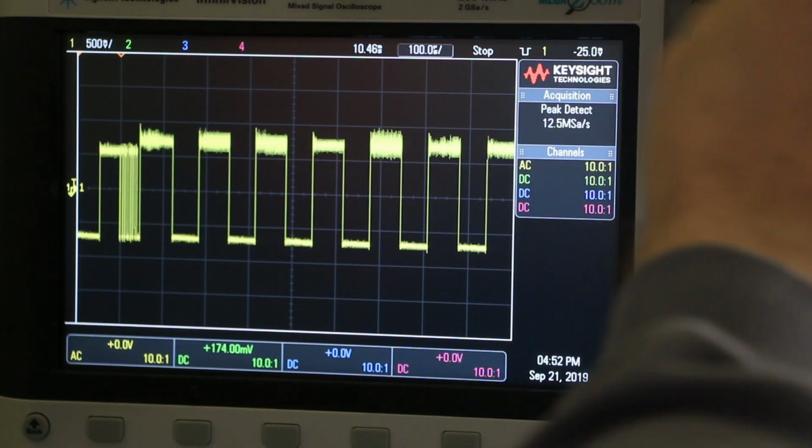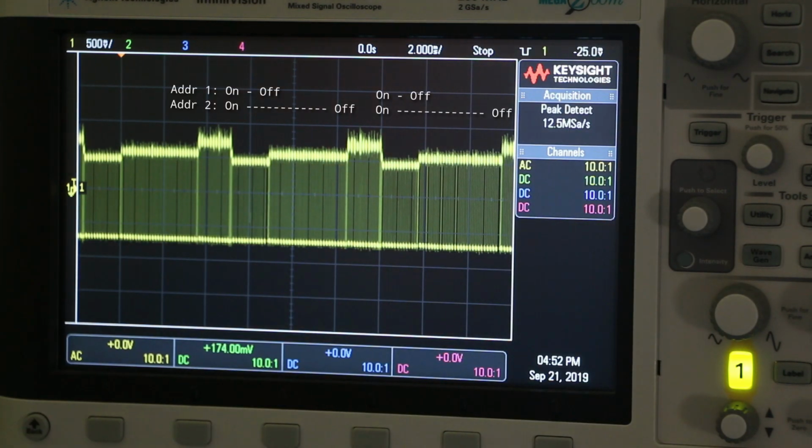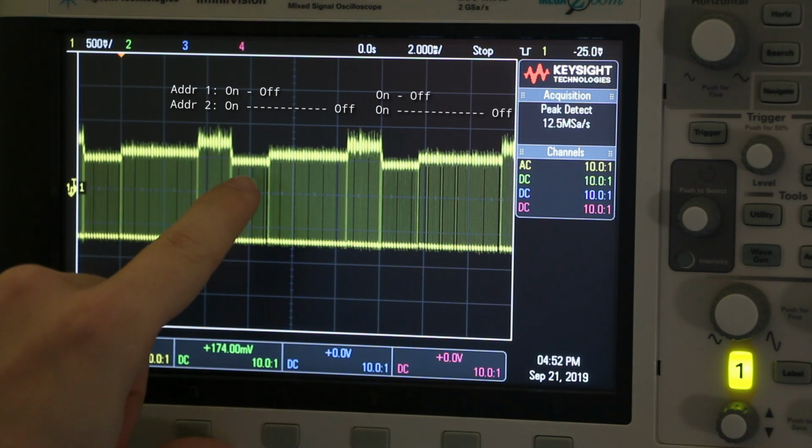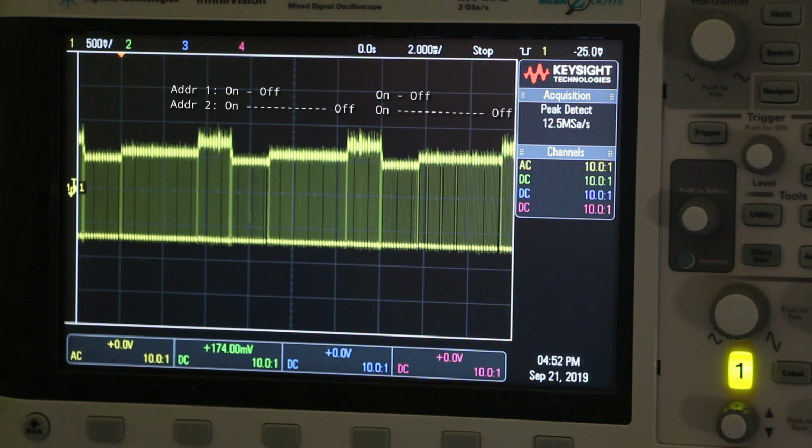So if we put that together, we can start to write onto or assign values onto this waveform here. And we were quite correct in expecting that the low signal here was all of the LEDs on, providing an extra drain through that resistor. The middle has one set of LEDs and the top has no LEDs turned on.